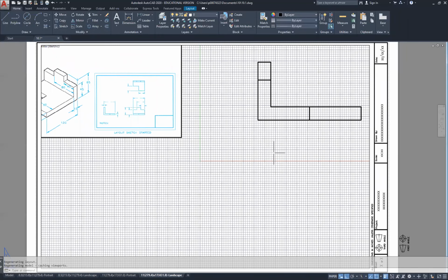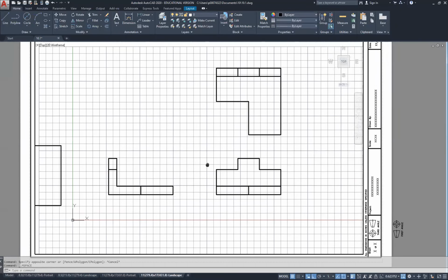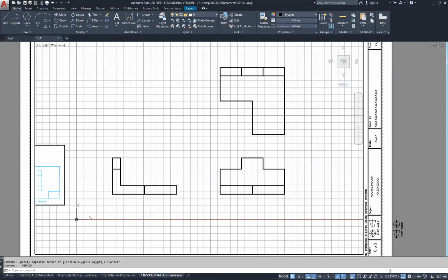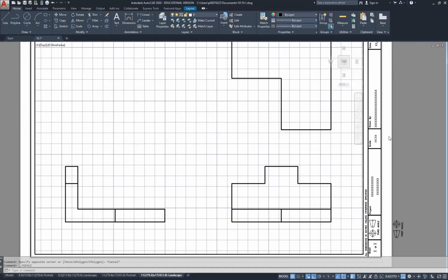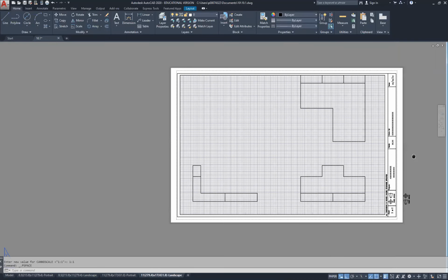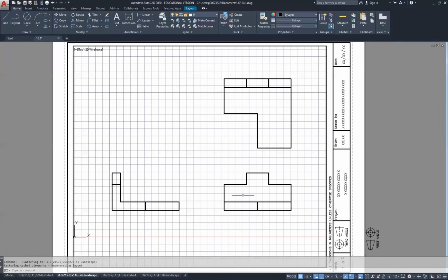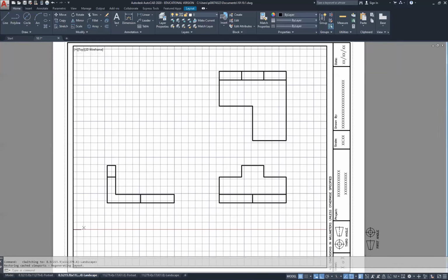Or we go to landscape, 11 by 17. Set that in there. Change this to 1:1. And at 1:1, this still doesn't quite fit. So I believe our best option, we're going to have to go on half scale on both of these to make it fit. I think our 8.5 by 11 would be the best sheet to use. So our scale is going to be 1:2, which is a half scale value.